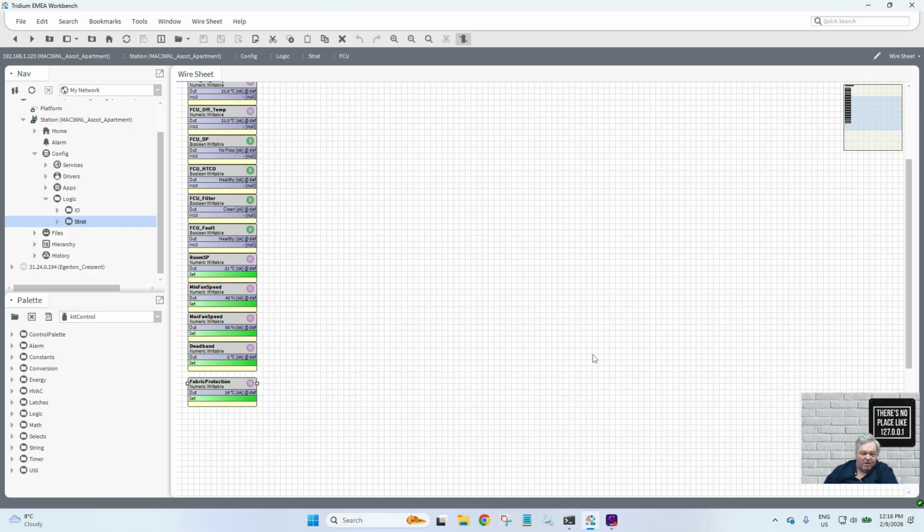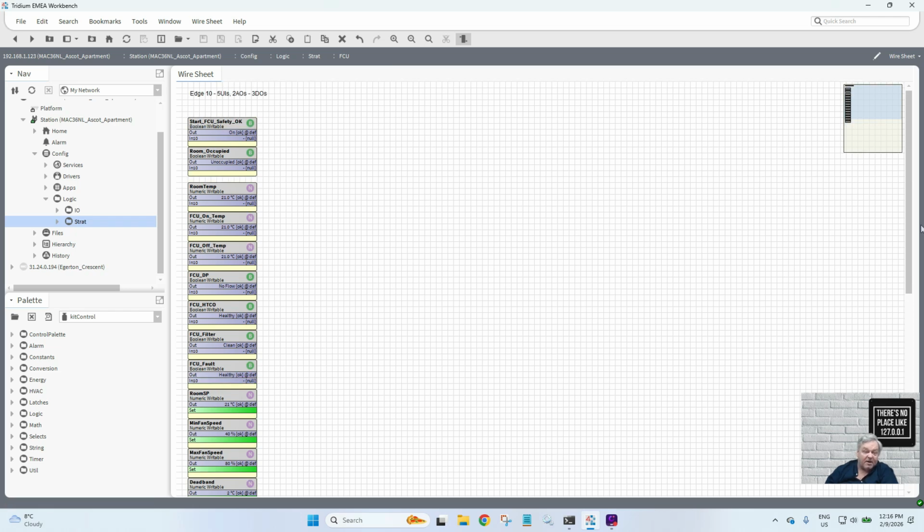So that's our inputs and our adjustments, and I can't think of anything else at this time. I think we've gone OTT, definitely gone over the top there, and we certainly haven't got enough UIs and AOs and DOs to do all this. Well, I don't know about DOs and AOs, but if we're using fan speed and we're using a heating coil and a cooling coil, we certainly haven't got enough AOs. And DOs, fan enable, yeah.